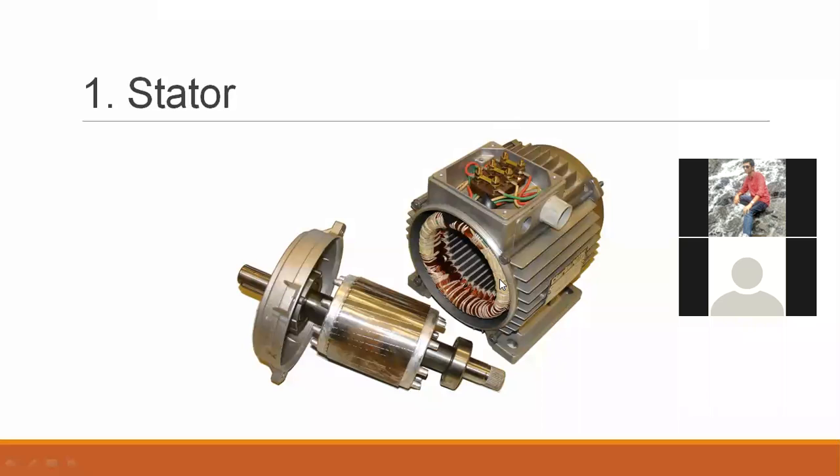Now, the stator winding, as we have seen in the working principle of the induction motor, is based on Faraday's law of electromagnetic induction. Whenever we give a three-phase AC input to the stator winding of the induction motor, the three-phase current flows through the stator and creates three different fluxes. Suppose I call the R phase, Y phase, and B phase the three basic phases. Whenever the three-phase supply is connected to the stator winding, three different phase currents flow through it.